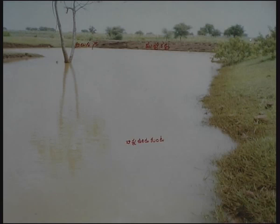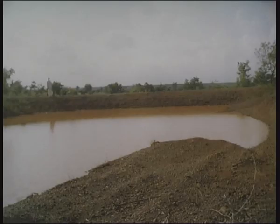But if a check dam is intended to be constructed in the mainstream course, where a maximum flood of a very high intensity could come up, it is not possible to construct an earthen dam at the central portion of the stream, because the flood discharge would be very high, and to negotiate that high discharge, a long surplus weir would be needed on the flanks.